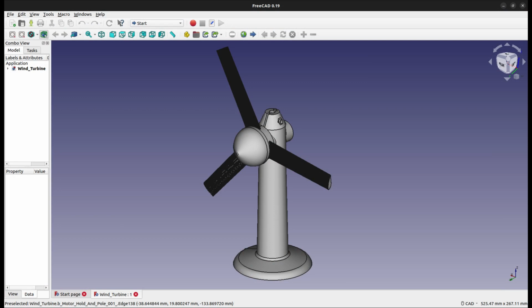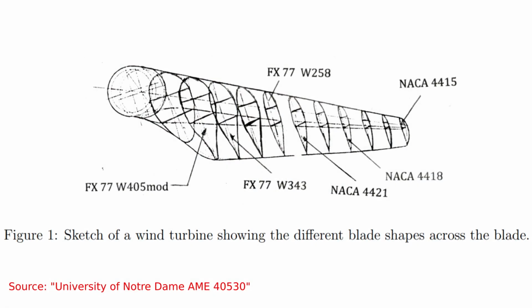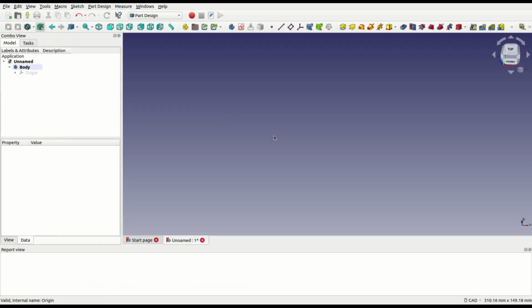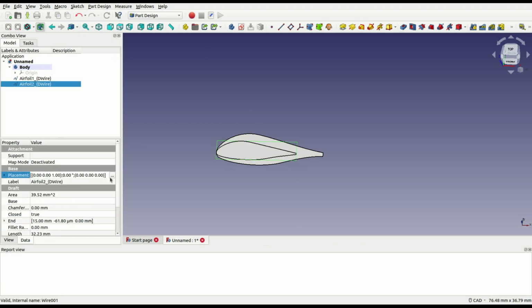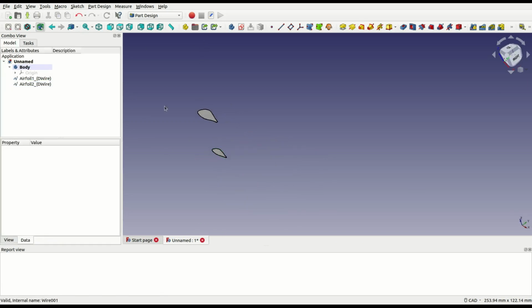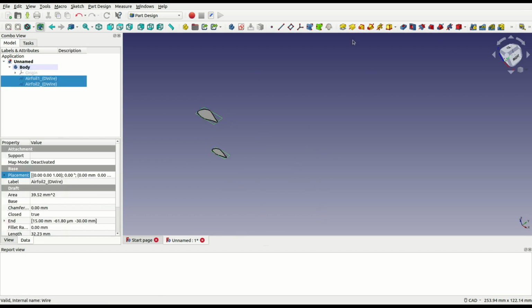Here's the turbine. I modeled it in FreeCAD. It's composed of a turbine stand, a middle hub, blades, and a dome. It all started with the blades. I looked online for wind turbine blade design and found this. So I looked for the airfoils, found only a few, and improvised. Pretty much making sure it looked legit and that the blade tips weren't too thin so I wouldn't have any issues with printing them. I used a macro to import the airfoils and created a loft between them.